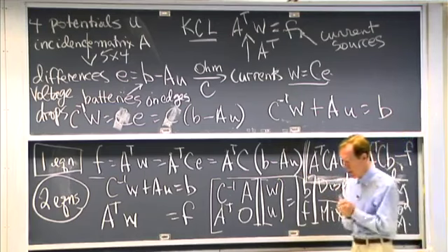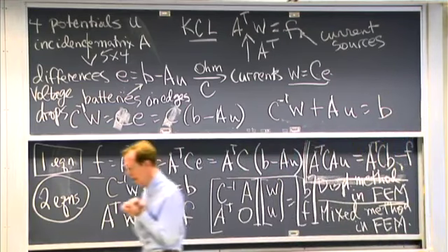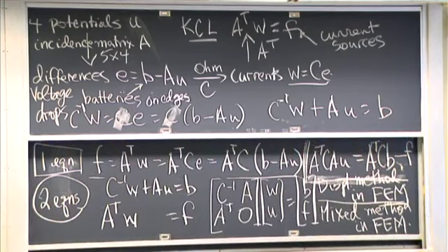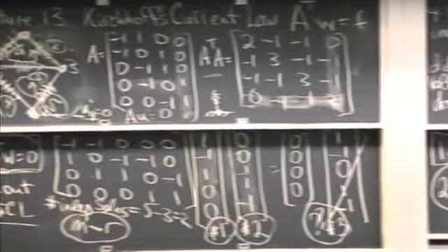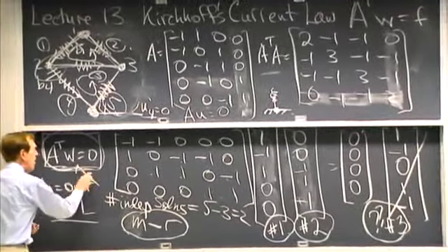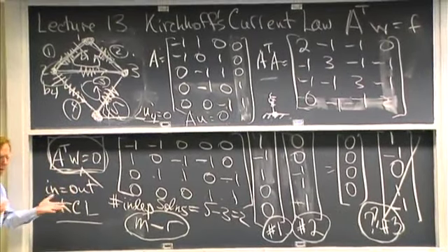Professor Pian in course 16, now retired, was one of the major developers of the stress method. The difficulty with the stress method, the reason it didn't win big time, is that the W's, if you make them the unknowns, you've got a constraint on them. Kirchhoff's, not all W's are allowed.